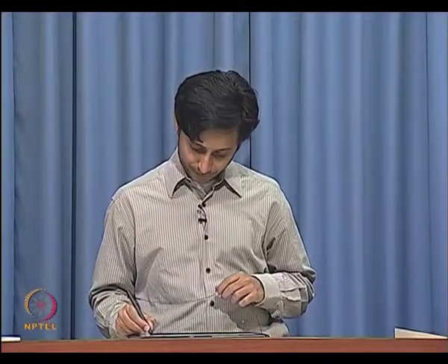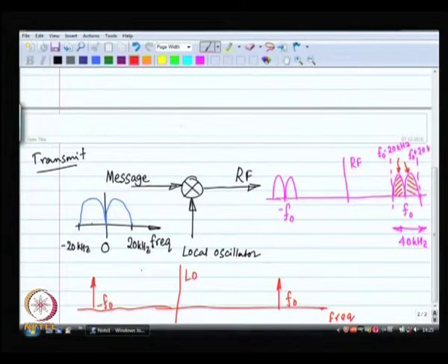So, we do not want to transmit both of these. Spectrum is a valuable resource, costs a lot of money, and we are just wasting half of our money over here, and it is very wasteful, no good. Both the lobes contain the same amount of information, the very same thing. So, let us get rid of one.